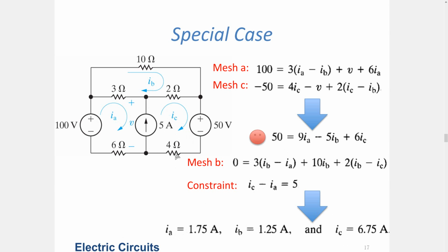So all the currents of the other components are a linear combination of these mesh currents, and they can be expressed. From there, I can write down the voltage drops, and I can calculate all the node voltages and the branch currents, which means that I can actually calculate the powers and everything. That's how we solve using the mesh currents.